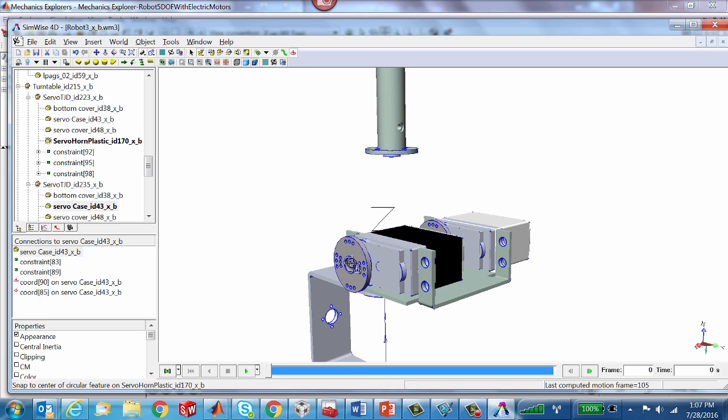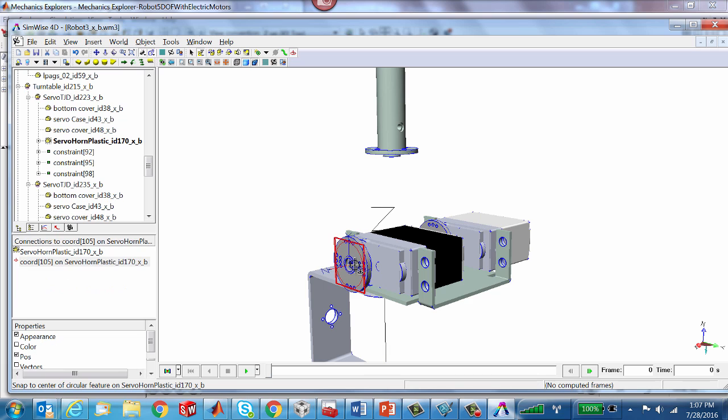The key to putting these frames in is you'll notice these blue circles when I'm doing it. Those are circular features that the tool has detected, and if I hover my mouse over any of these blue circles, I see an icon for the frame tool, the coordinate frame tool, that looks like that. If I move it over here, it's a regular image. If I move it there, it detects a surface, stuff like that. Anyways, let's go ahead and create our next one.